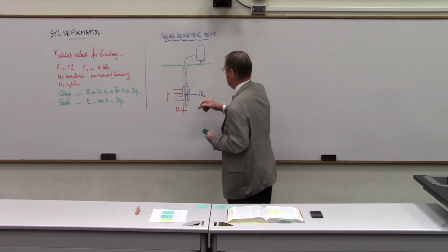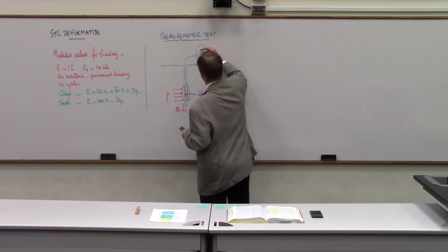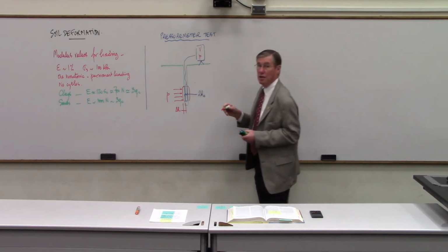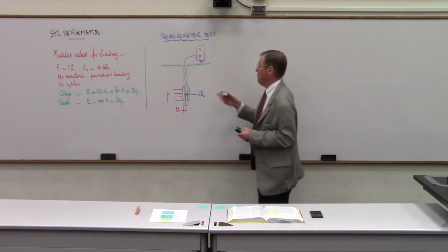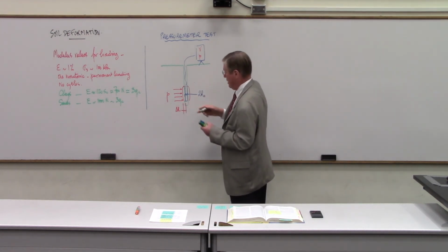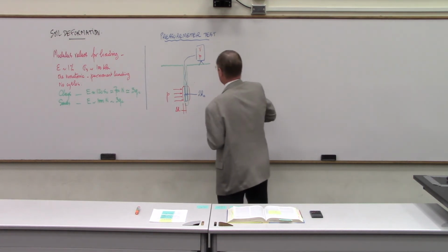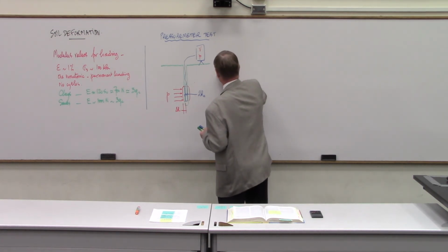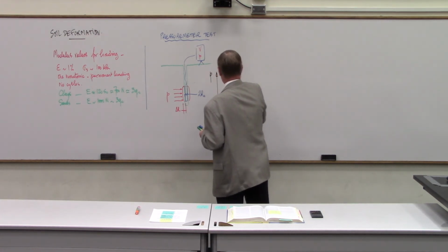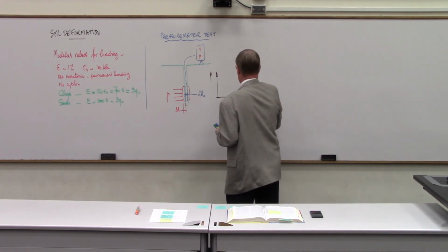And delta R, so you measure here the volume, basically, and the pressure on the gauge. So the volume of water that you inject in the probe is measured, and from the volume injected, you can back calculate the relative increase in radius of that cylinder. And then you plot a curve that looks like this, P versus delta R over R0.